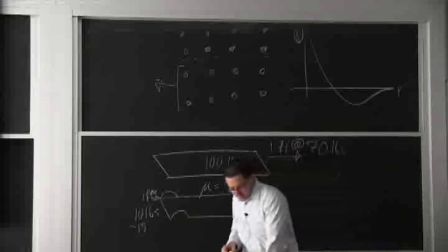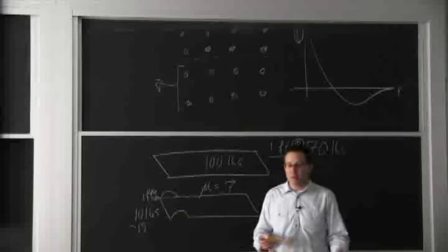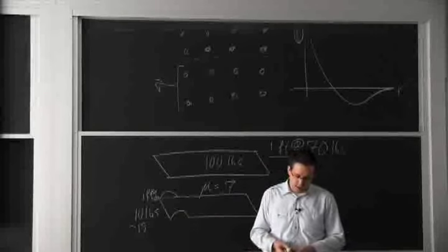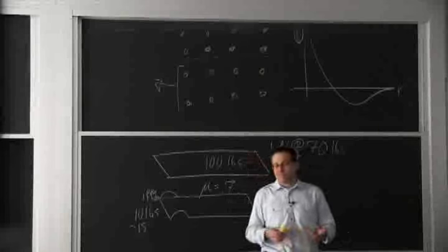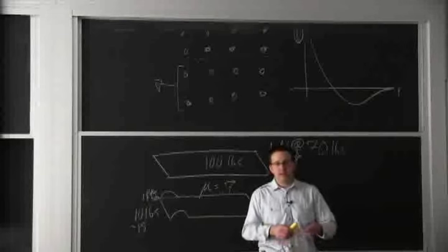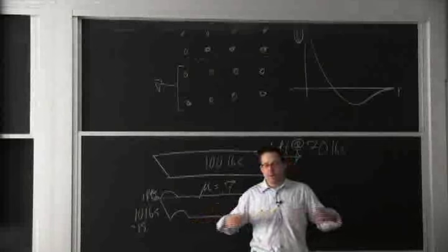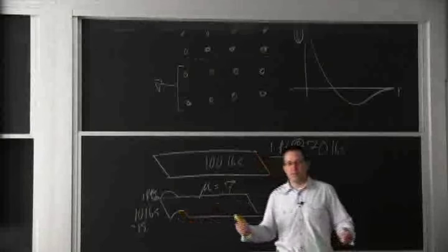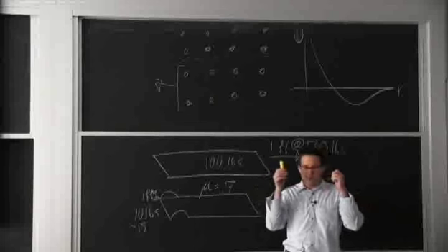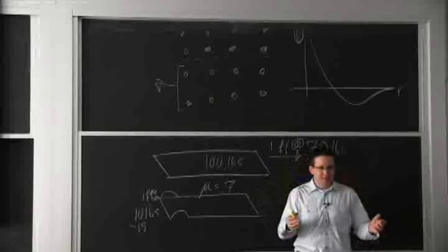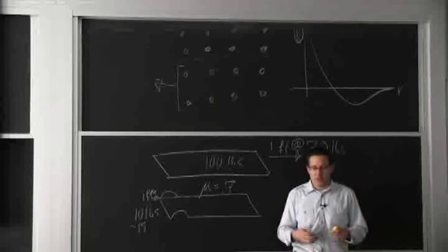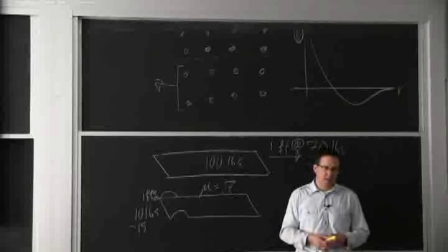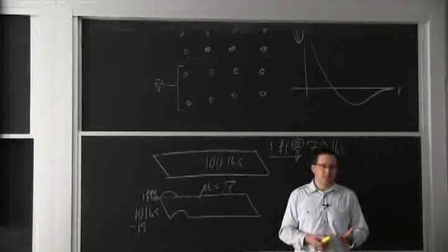Now, I mentioned that plasticity is used in forming. Elasticity, we all know, is used for a large number of applications. A lot of times when we talk about springs here, springs are most often pieces of steel that we will deform and deform and deform, multiply the dislocations, make a lot of folds in them. So now when we put them in your car, they're very stiff. They don't deform anymore. They have so many obstacles built in that it'd be really hard to create a permanent deformation in them. So that's how we raise the yield strength of a lot of metals.